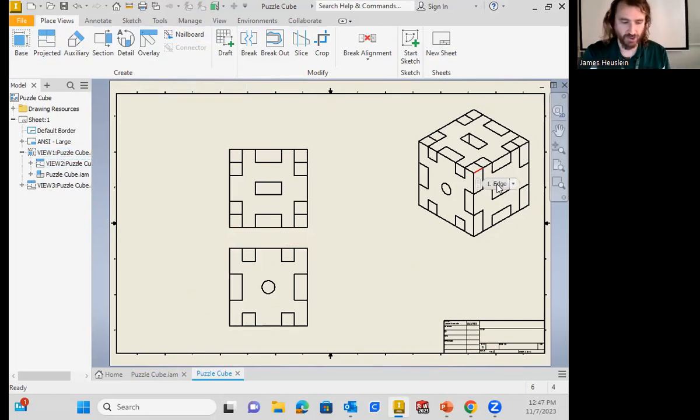Now, in assembly drawings for my class particularly, we do not add dimensions to an assembly drawing, as an assembly drawing is just to communicate how this was put together, what was used to put this assembly together, what part files, etc., were used. So all the dimensions will be put into the part drawing file rather than the assembly drawing file. We can get dimensions if we need to from these individual pieces, not from this assembly. Okay, so we projected our views in there. So we're not adding dimensions to an assembly.